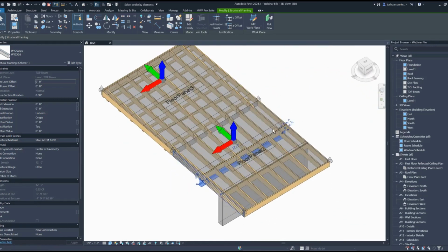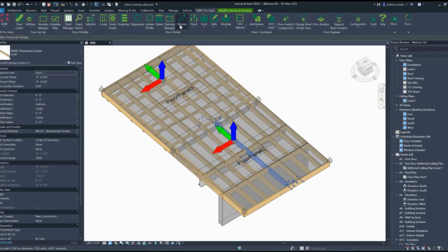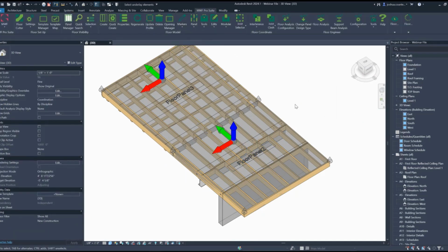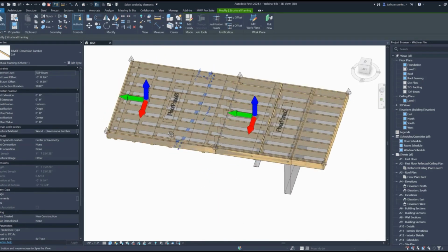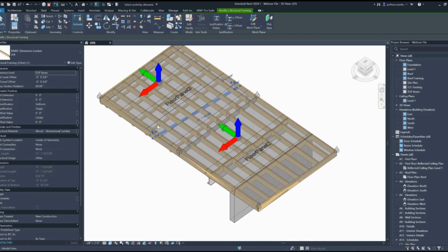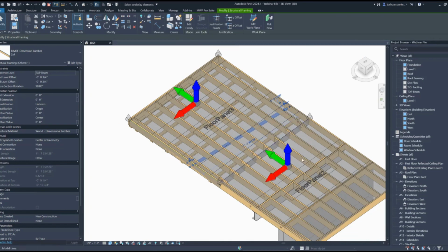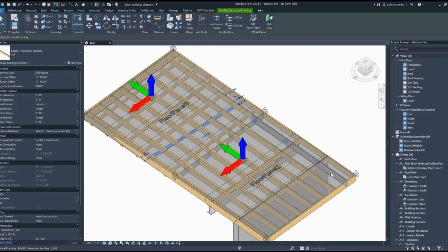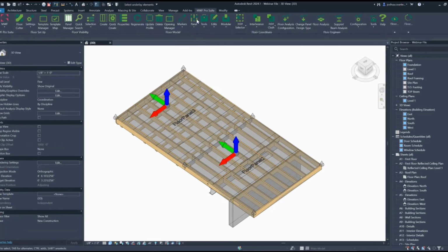So you can apply different marker line patterns. You can apply it multiple times to a floor panel. You can assign different bridging types. Maybe you want to do squash blocks, or you need some joist support throughout the panel. You could utilize some different settings throughout the tools that we just kind of did a breeze through.